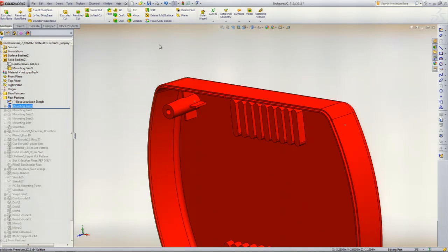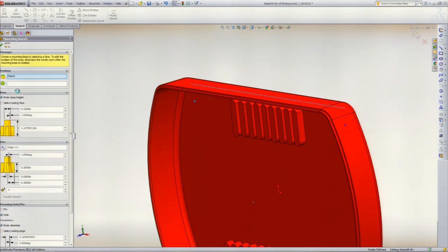Okay, if I understood you correctly, the diameter of the boss itself would depend on the functionality of the boss. If you're only going to be using a self-tapping screw going into the boss, you can probably get away with a smaller ID. If you're going to be adding an ultrasonic insert into the boss, typically you have a minimum boss diameter that the insert manufacturer recommends for hoop strength and mechanical bonding of the insert into the boss. So that will vary, but let me just backtrack here for a little clarification.